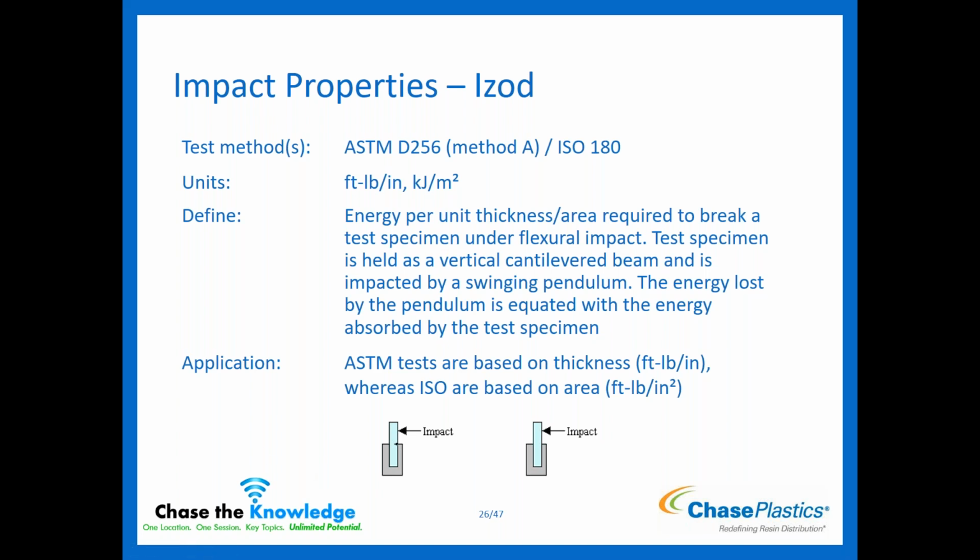For the test itself, the big difference between your Charpy and Izod is going to be how the part is held and how it's impacted. This is what it looks like. It's being held in a device here, and the pendulum will come down and hit it. On the next slide, I have another picture for you. That's going to be different than your Charpy, which we'll talk about after.